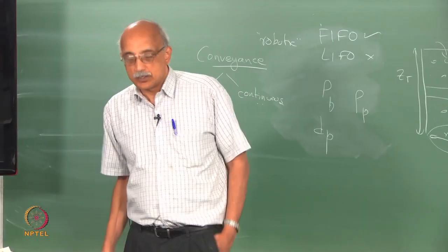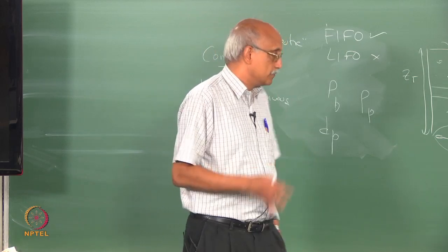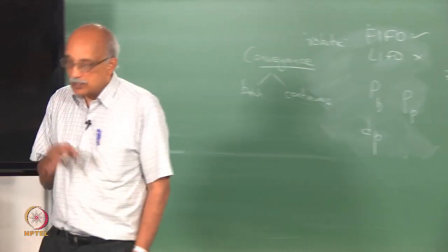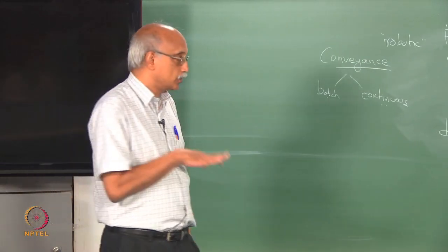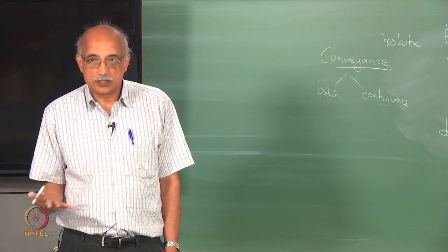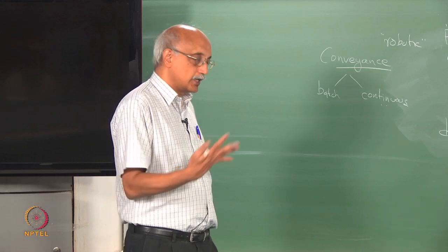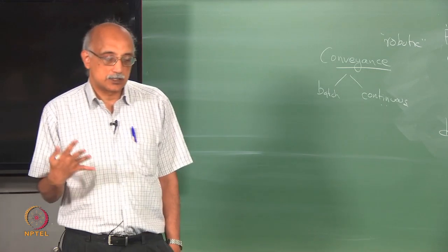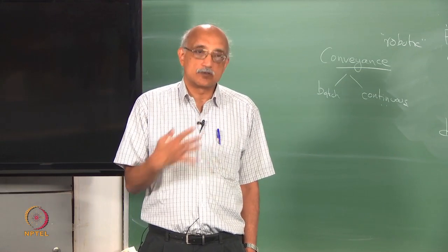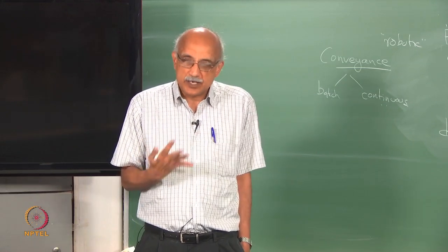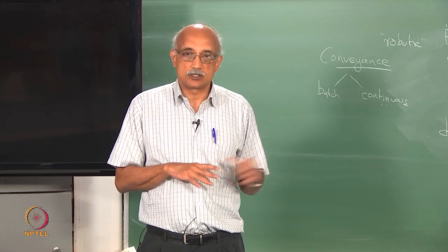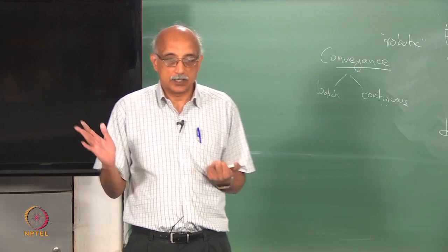So, wherever possible, think of ways in which you can reduce the time involved as well as the amount of force that you have to apply, because it all corresponds to energy, work and energy, right. And just like with any mechanical operation, the real challenge is how do you get the work done with minimum investment of energy, because most mechanical operations are brute force kind of techniques, whether we are talking about size reduction or storage and handling or conveyance.